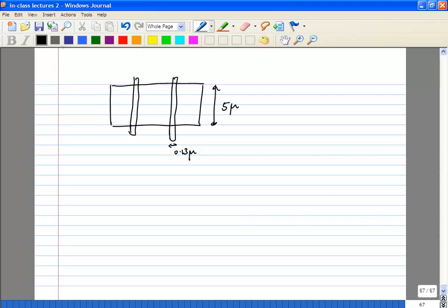And then you can do dual gate contacts also, and that's okay. So this is called a multi-fingered layout. You can increase the number of fingers and trade off your gate resistance. In this case obviously your gate resistance is half in a coarse way.